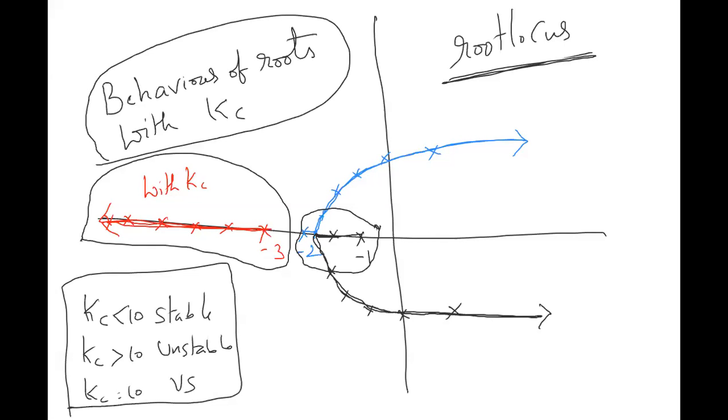But what is a band? Band equal to 100% is, let's take this problem: Kc up to 10 is stable, but in the plant, I don't want to take risk more than 4.5. Where did this 4.5 come from? Ziegler-Nichols settings. Where do the Ziegler-Nichols settings come from? Multiple plants. When the concept of control started, say 200, 300 years ago, somebody might have put Kc equal to 10 also. So they faced a problem. Then somebody realized that Kc equal to 9 is good, then Kc equal to 8 is good. That is how the experience from the multiple plants is consolidated and put into a theory called Ziegler-Nichols settings,